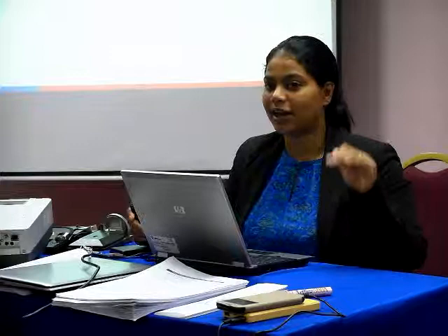currently in MV overhead line, we are doing condition-based maintenance. So condition-based maintenance right now, there's visual inspection, infrared, and ultrasound. So these 3 condition-based maintenance will not tackle the problem of corroded pin insulator. So what actually do we need to solve this problem?